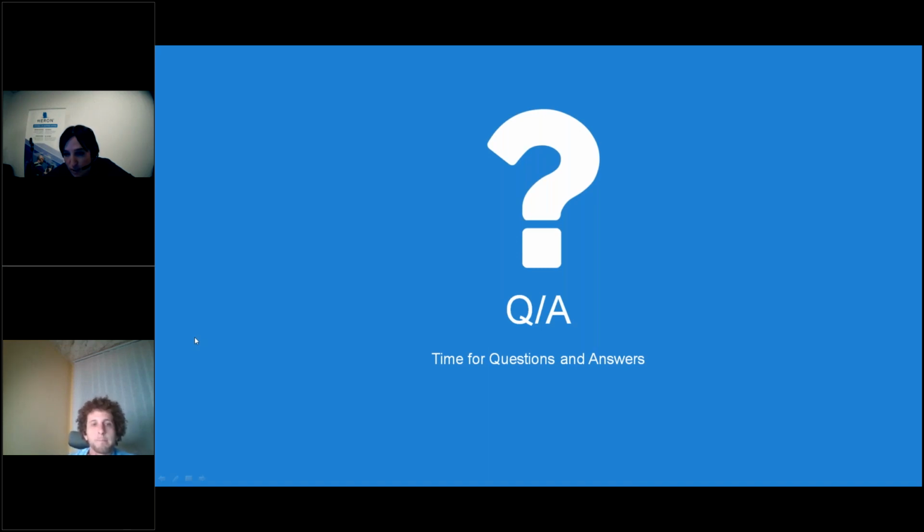Can we import raw data scans and align in Reconstructor? I think that, Daniel, we can also reply together. Yes, you can import some raw data inside Reconstructor, and you can align the data in Reconstructor. We do have different registration possibilities: target-less registration, target-based registration, and manual registration.